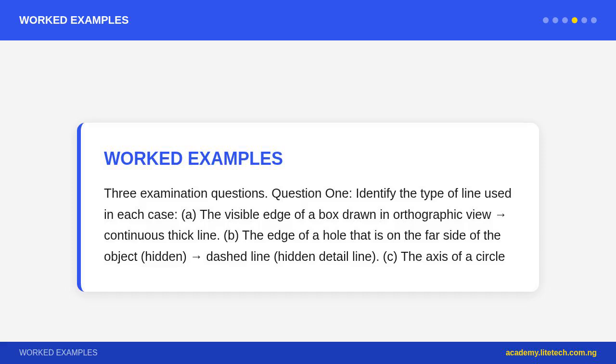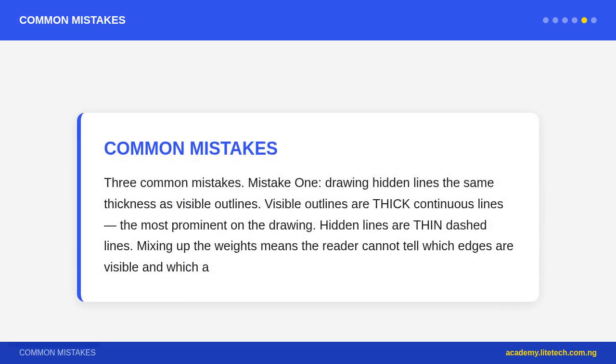Question 2. Draw a 70 mm horizontal line, then from its midpoint draw a vertical line of 50 mm, and label both with dimensions. Step-by-step instruction: use a T-square for the horizontal line, measure 70 mm with a steel rule, mark the midpoint at 35 mm, use a set square plus T-square for the vertical line at the midpoint, extend 25 mm above and 25 mm below to give 50 mm total vertical length, add dimension lines with arrows and write 70 and 50 against the lines.